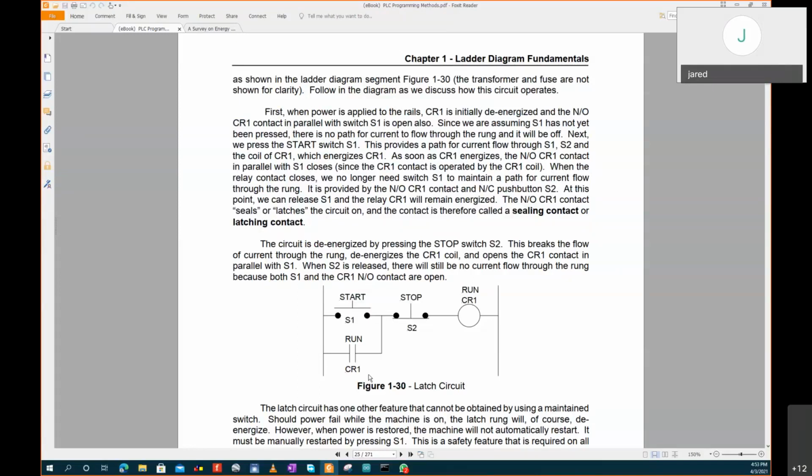Okay, this is the NO of the relay. So we're talking about the relay contact here, normally open, because you can see for a normally closed it's always crossed, but because it's normally open, it opens. Since this is on, power will be available here. This circuit will continue flowing continuously, because once this became energized, it is high, and because of this holding circuit, look at the way it is, it's this way. So this circuit is complete and it continues being powered forever. That is what we mean by a holding circuit.